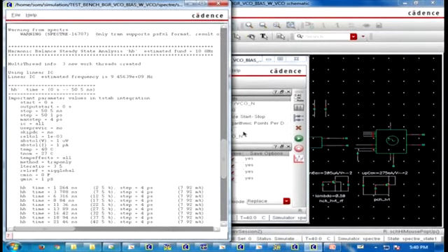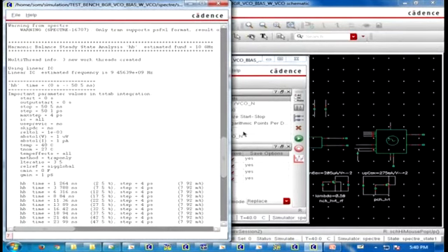It's packaging. So the loop, what is the length and how do you loop it, that tells you what will be the inductance of this. That is extremely important. And when two parallel such inductor loops are there, then capacitance will be added. That will shift your frequency again. So don't use parallel loops here and there.